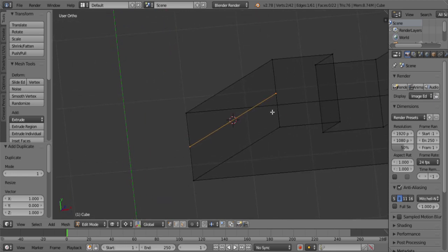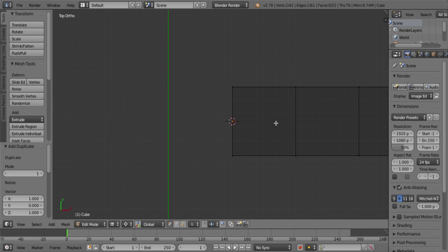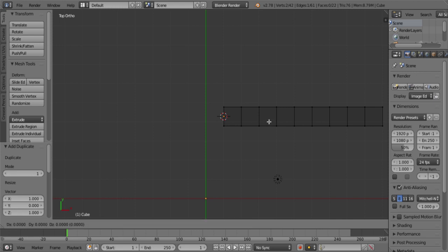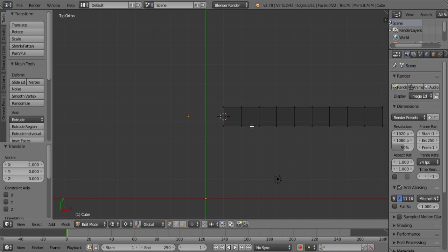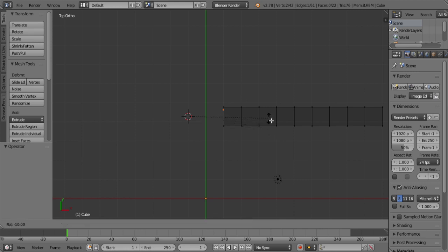Switch back to top view again. Now this is going to be interesting. I'm going to scroll out a bit. I'm going to position my cursor in the center of the tower. I press G, take 2 steps to the left, Shift S, snap cursor to selected, and now I'm going to press undo, Ctrl Z. So this line is back to where it was. Now I'm going to rotate. I press R. Let's say, hold on Control, about 30 degrees.